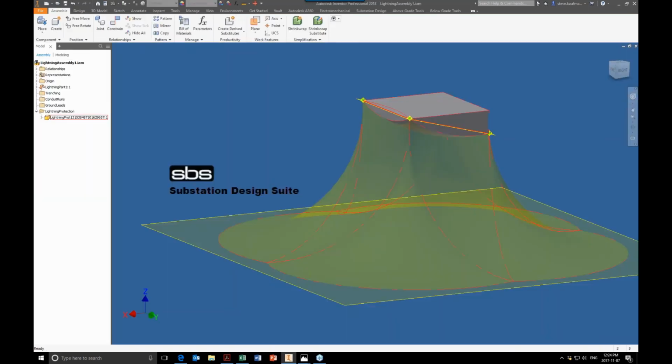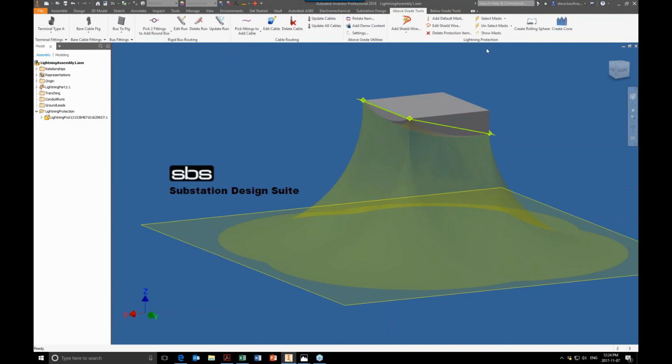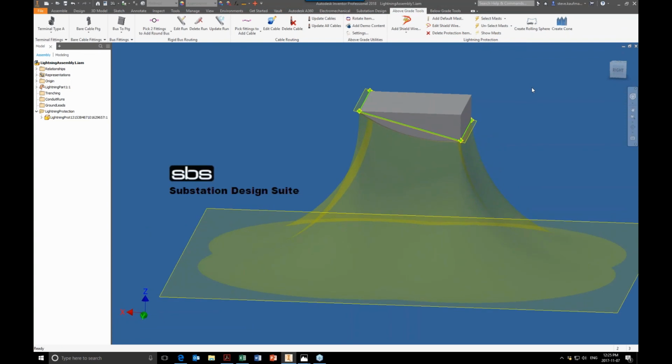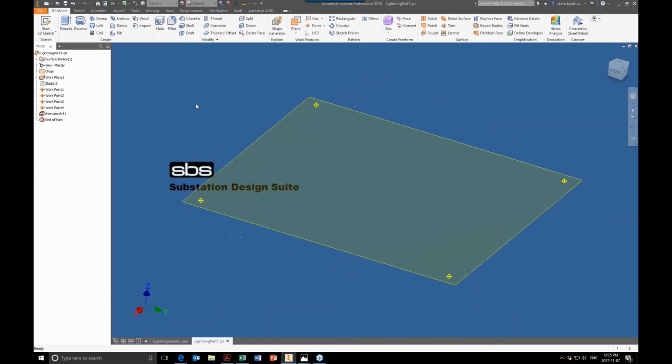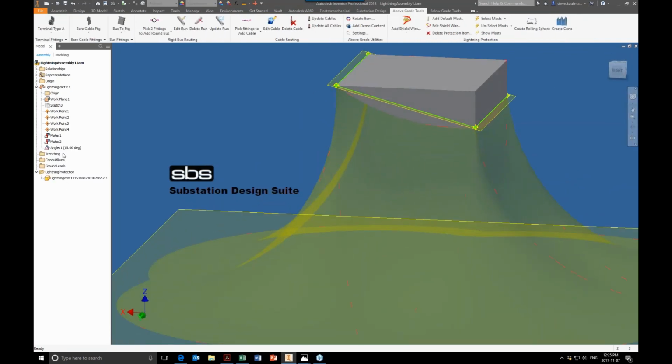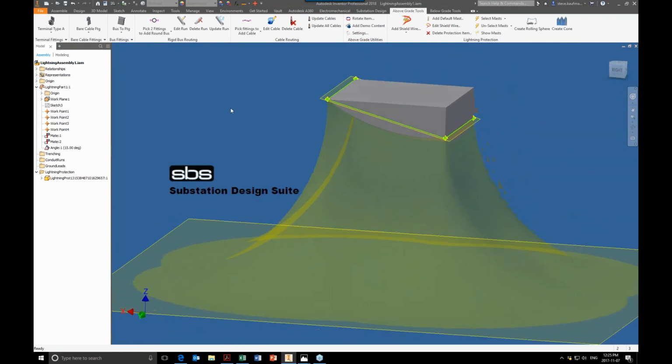And the same idea of putting 4 points, because lightning works on points as well. We can select masts or points. If you're working with some lightning and trying to come up with an idea on where to put your masts, and you don't want to build a mast and stick it and start playing with it, I'm thinking of this type of thing: just putting 4 points on the plane, right? This plane, I put it on an angle, or did I? Oh, I put it on the angle in the assembly. So I put 4 points on this plane, and then I just pick points. I constrained it on a 15-degree angle. So I put that plane in here, and I ran it here.